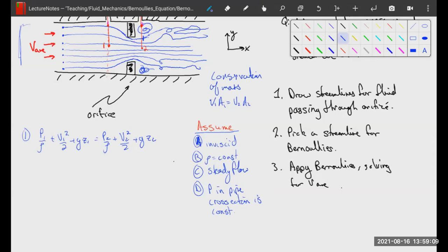Okay, so great. Let's look at this. We're measuring P1 minus P2. That's what a differential pressure sensor does. It measures the difference in pressure across it. So we know we're going to have to bring P1 and P2 together. So effectively, that removes one of them as an unknown. In fact, they're both known because we're measuring the differential pressure. We have no change in height, so we can actually cross out our z's, right? Make those equal to 0. And all that's left is a difference in velocity, right? Okay, so let's write 1 to 2. We have, let's bring our pressures together.